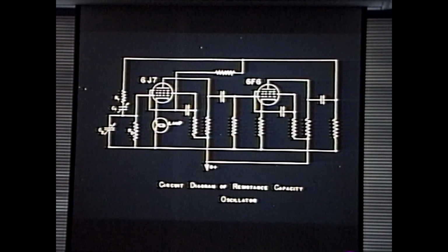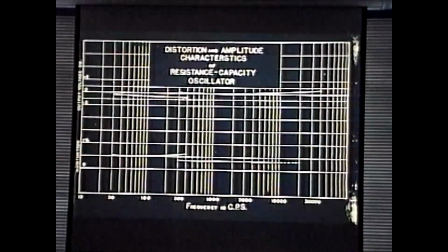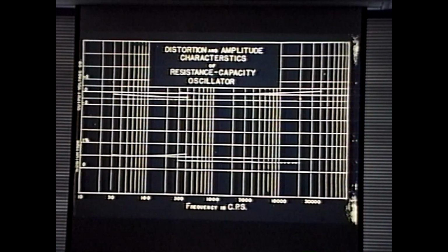Not bad for that at all, especially when you consider that the lamp cannot tell the difference between amplitude-induced changes in its impedance and ambient temperature changes. As ambient temperature changes, the dissipation constant of the lamp changes, its resistance changes, and it has no way of discriminating that from an output change to which it's supposed to respond. So the crucial piece of information that's missing here is over what range of ambient temperature was this output flatness plotted. But knowing HP and their fundamental honest integrity with regards to specs, I assume it was pretty clean.